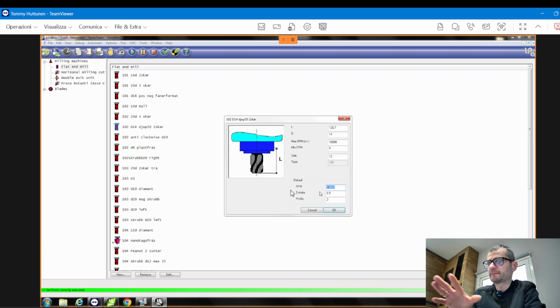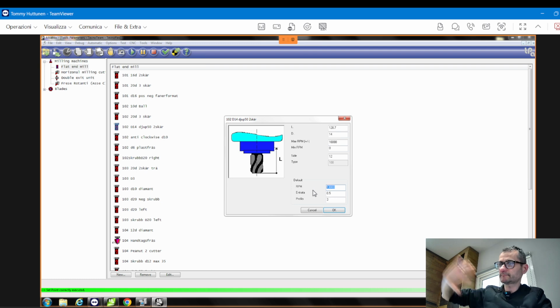This parameter, for example, when you go down 0.5 and 3, we can say it's a slow, medium-slow speed. So I don't say that it's okay for all the tools that you have, but maybe yes, and maybe in the future you will increase this speed, because it's more or less slow speeds. Okay. Remember one thing: the RPM is the same as in AlphaCam. So you have to put the same numbers. If it's 18,000, you write 18,000.